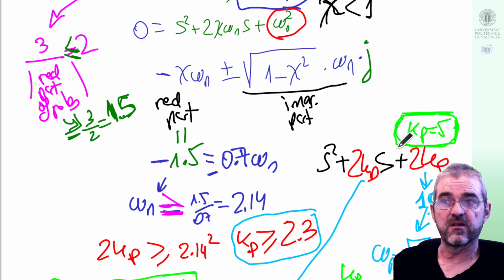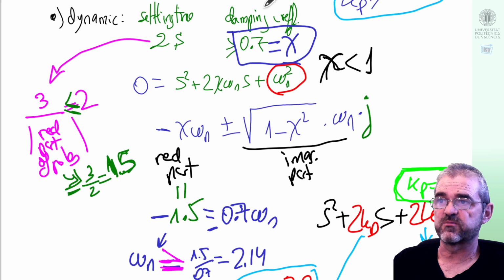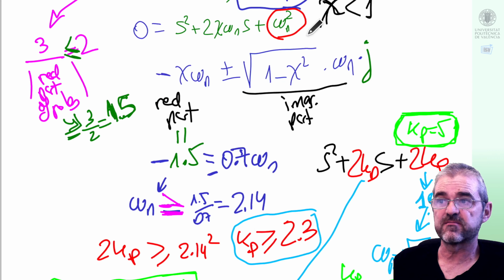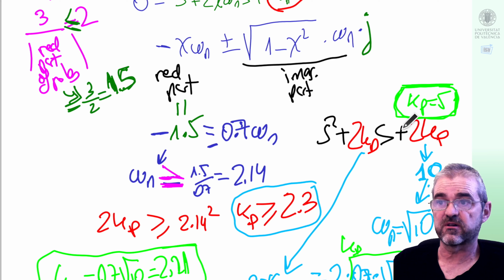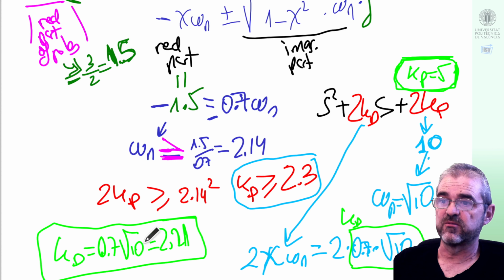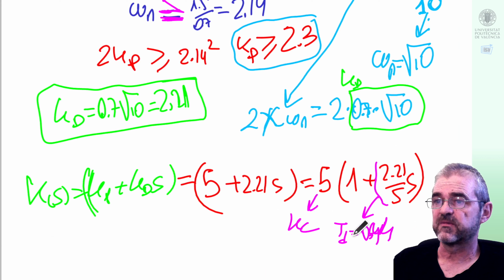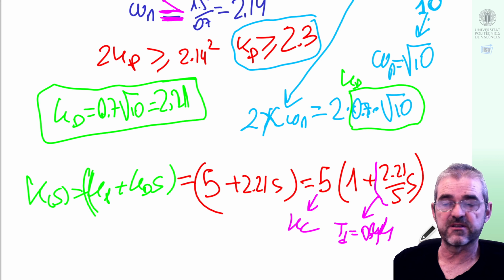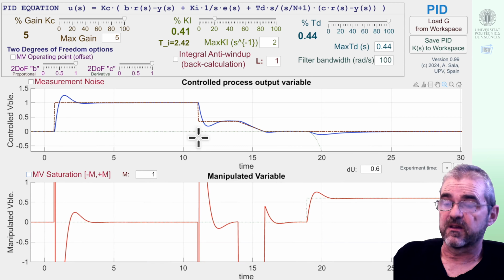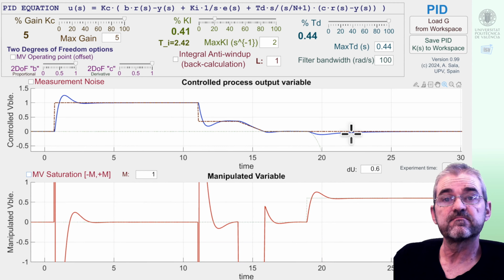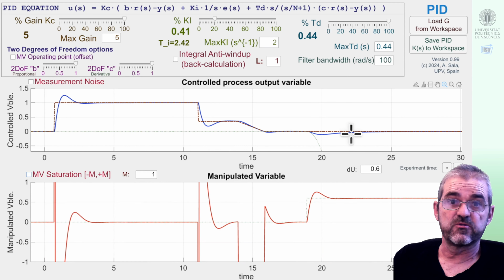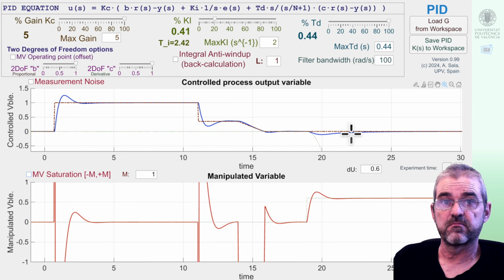That, okay, the error one was the winner, and then we, with this 0.7 damping coefficient, were able to construct the desired denominator of the transfer functions and compute my proportional derivative gains, which transform to the parameterization in my particular simulation, gave me a very nice simulation in accordance to what was requested.